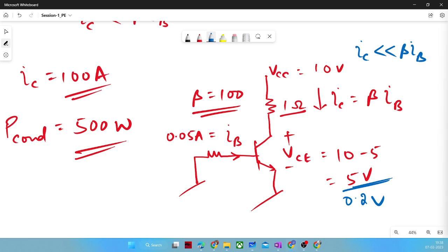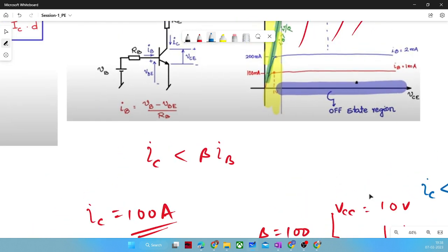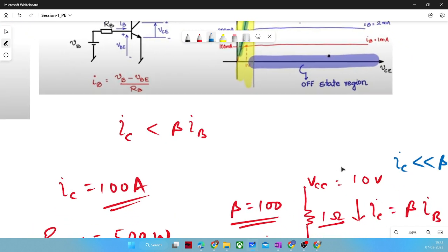Hello, can I ask a question? Yeah, please go ahead. It is related to the previous question. The conduction loss of any switching waveform is VCE sat into I into D. Here, in D, we have to consider turn on and turn off as well. Is it considered, or do we have to consider it separately?